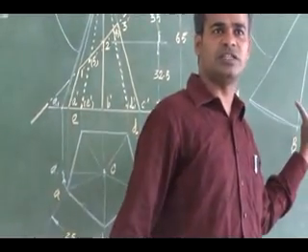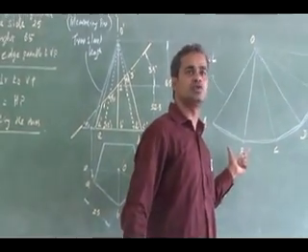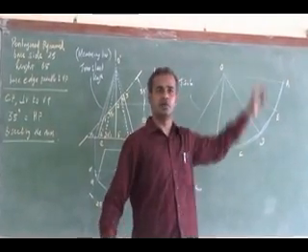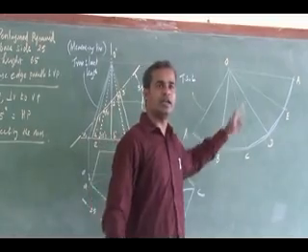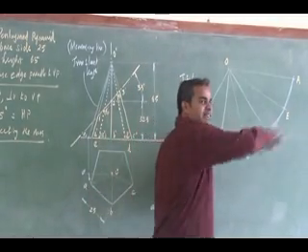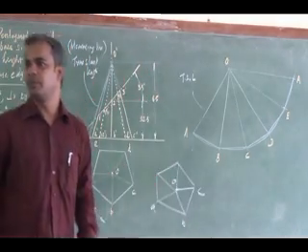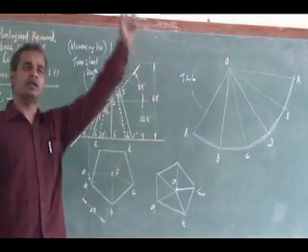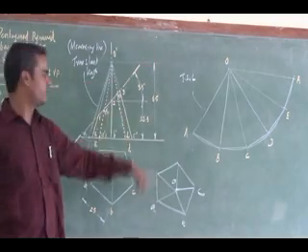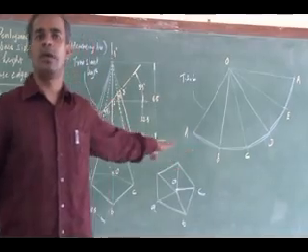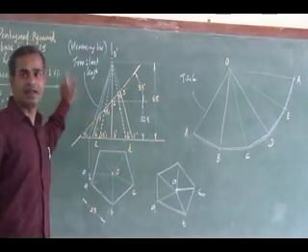You can cut. If it is a pentagon, 5 times. If it is a square, 4 times you have to cut. If it is a hexagon, 6 times you have to cut it. Then you have to connect it. Finally, you have to connect the base corners with a straight line. For a cone, you won't connect it; it will be like a curve. For a pyramid, you have to connect it like this. Is it clear? For a pyramid, you need a true slant length.